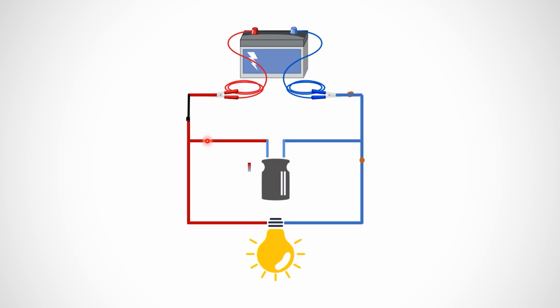If we turn it back on, we see we have current again flowing into the capacitor till it's full, and if we turn off again, we see our bulb doesn't die out. It uses energy from the capacitor to continue being on, and as long as the capacitor is connected and has charge, current continues to flow from the capacitor into the bulb and we will have no blink.